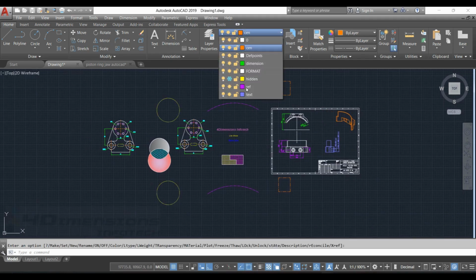To freeze the layers, suppose I go to the layer tab. Now I'm going to take this hidden line layer. Just click on this option, say freeze layers. Whatever objects are made by this layer will be frozen here, meaning the transparency will be removed. They will be hidden here. We can see this layer has been frozen and all the parts made by this particular layer have been hidden here. The same is the command of turn on and off.